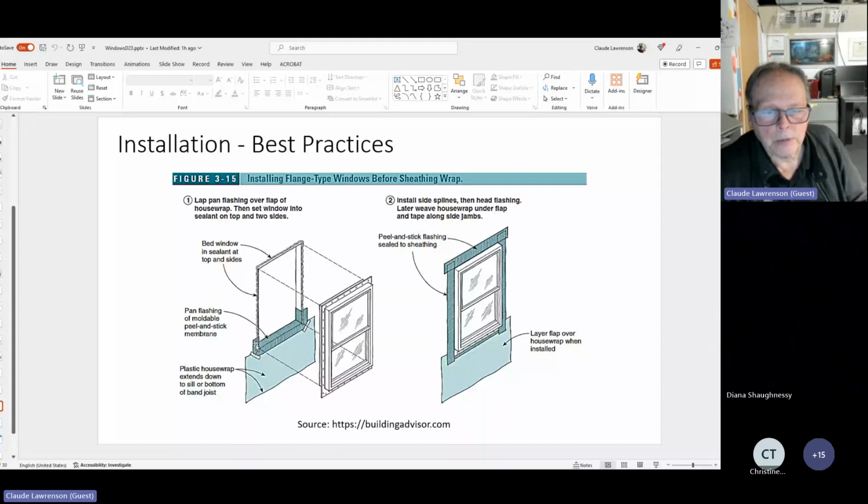Basically, this is where I would start, and then go all around the window, and at some point certainly install the window. I like to go up all the sides and certainly even the top. Hey, a little more is better protection. I don't have to think about doing it again later, or some of the implications of why I didn't do it. I should have done it. So basically in installing it and then resealing it again, there are extra layers of protection. Number one, we're going to be cutting down on the potential leakage, and certainly when we're thinking about this, it's going to be very well sealed.